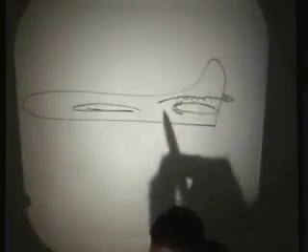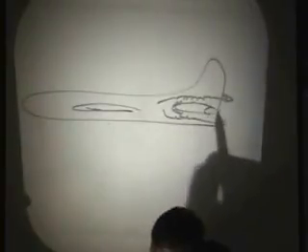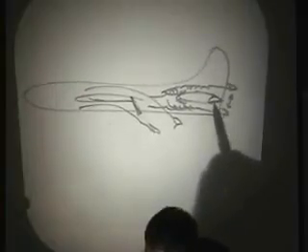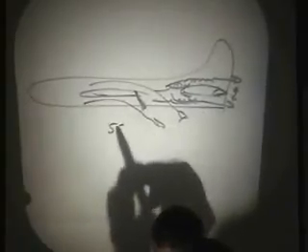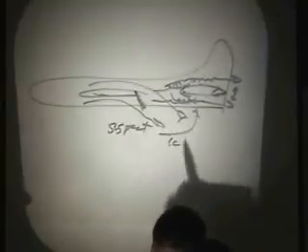So I'll draw a really deluxe airplane here, and here's our tail surface, and here's our main wing. And if we have icing on the tail here, it's going to disrupt our airflow, and the effectiveness of the elevator as it goes up and down is going to be less. But as soon as we put flaps in, it's going to make the airflow messed up even more. It's going to increase the turbulence across the tail, and it's going to reduce the effectiveness of the elevator. So if we're coming into land and we suspect icing on the tail,